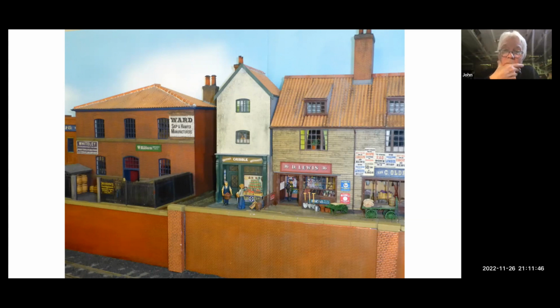So I'll carry on. What happens is that the laser beam comes out of the laser itself at about 3 millimeters diameter. It then hits a couple of mirrors, and then it comes to the laser head, which is a prism. It's diverted from horizontal into vertical, and passed through a focusing lens.